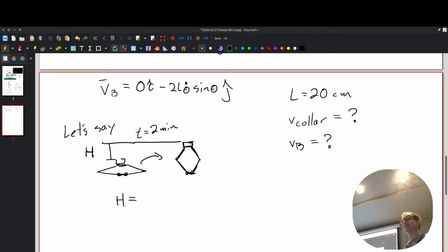But with and without the weight, you can only rotate it so fast, so you're limited by how quickly you can turn a crank. Most human ergonomics is around 1 rotation per second. You can push it a little faster to 2 rotations per second, but it's a little uncomfortable. If it's too slow, like 0.1, then it's very muscle fatiguing, like a deadlift. It's leg day.